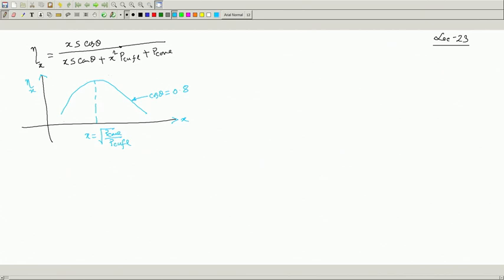And if you repeat the same thing for other power factors, these curves will be like this. This may be power factor cos theta 1, and for a lower power factor it may be 0.6. No point in attaching leading or lagging, efficiency will remain the same.